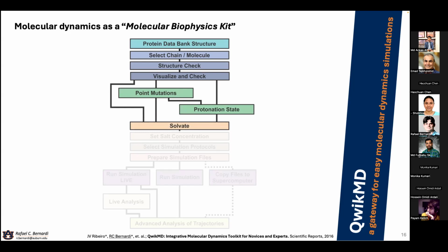And then for simulations, you need to solvate your system. You need to set the salt concentration. You need to select the protocols you want to run. We want to help you with all those steps. Then we're going to prepare all the files so that you have basically a folder with everything inside that you need to run. Okay?